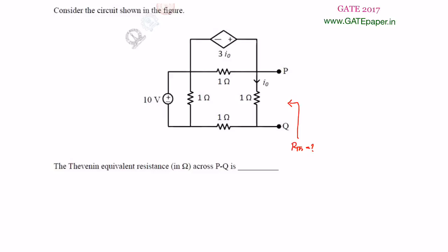across any two terminals, that is, at the terminals of interest where you want to calculate the Thevenin's resistance, you must apply a test voltage source, and because of that test voltage source you are going to get some current. The test voltage source is giving rise to some current. Get the ratio of test voltage to test current, that gives the Thevenin's resistance, when no other voltage sources or current sources, no other sources, are present in the circuit.